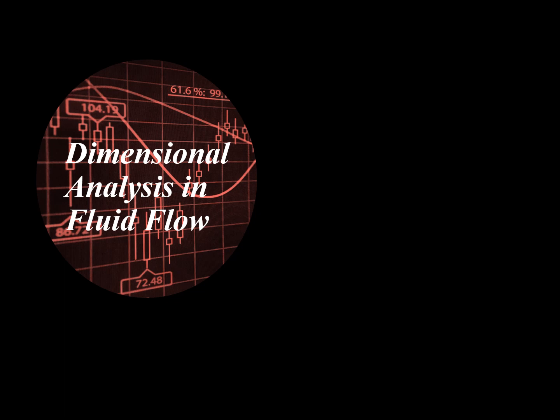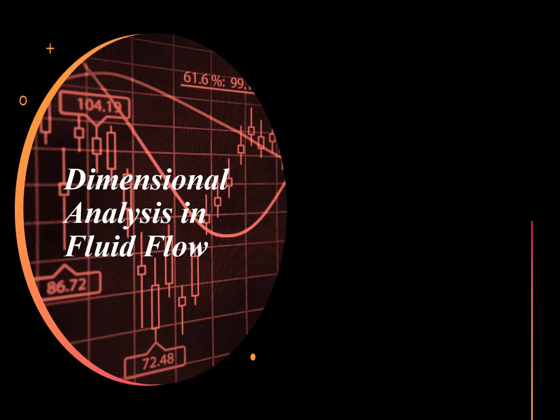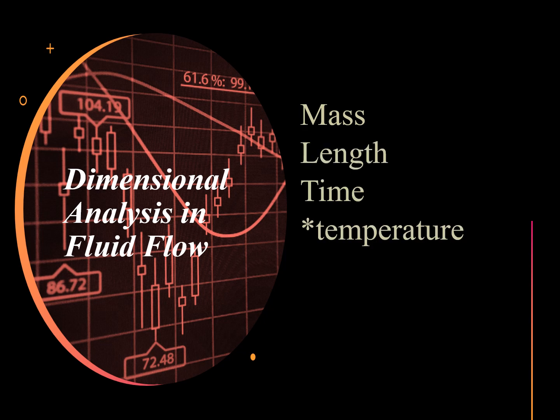We take note also that in dimensional analysis, we group the variables into dimensionless parameters, thus reducing the number of initial variables. Dimensions of the physical quantities may be expressed in terms of fundamentals like mass, length, time, and sometimes temperature and thermal energy. Because problems in fluid dynamics and heat transfer have many parameters, dimensional analysis reduces the number of variables, making the analysis less difficult.